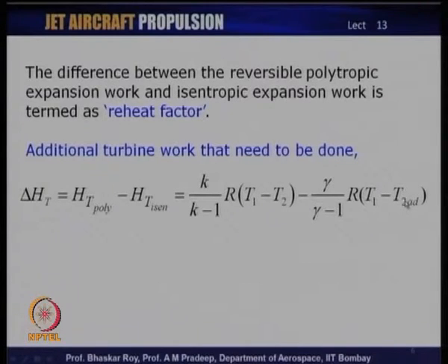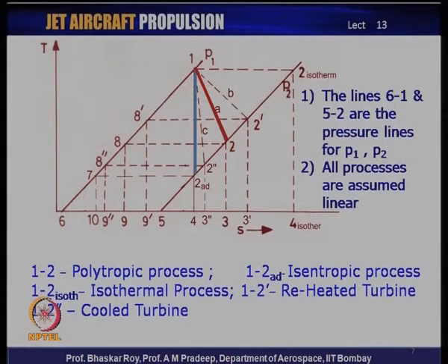So, the difference of the two is the extra work that the turbine needs to do to extract the work from the high energy gases, which means of course that much less work would be available on the shaft for supply to the compressor or to any other functionary in the jet engine. We will have a look at this reheat factor again in a few minutes.